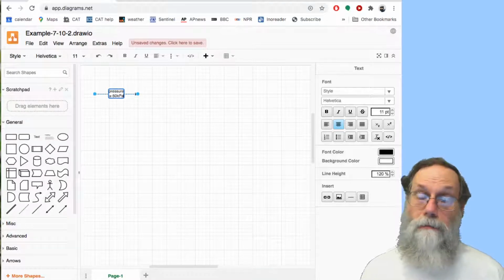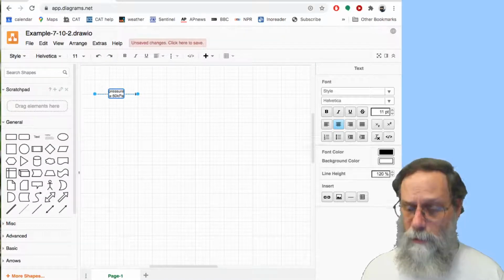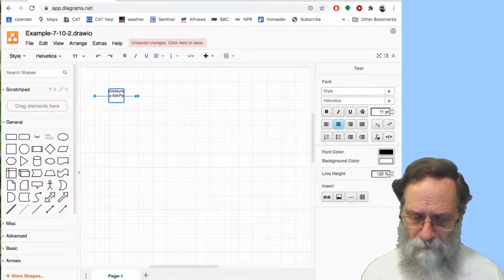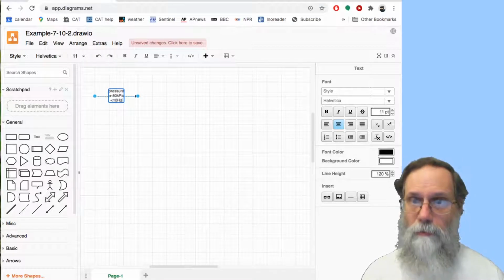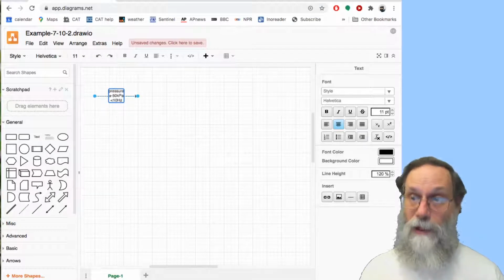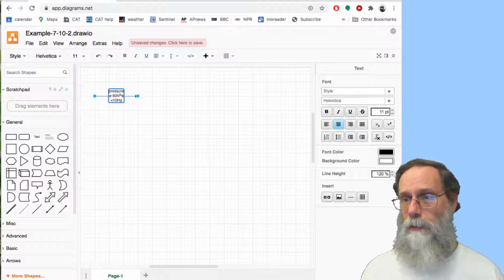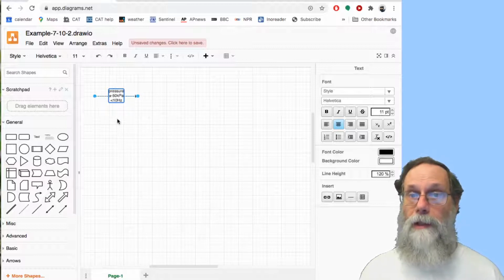And we need to know how fast the signal changes, perhaps. So let's say it's a fairly slow changing signal, but not real slow. Let's say less than 10 hertz. So we're interested in all the way down to DC. So we're interested in what is the actual pressure here, but we're not interested in really fast fluctuations in the pressure. Okay, so that's our signal.